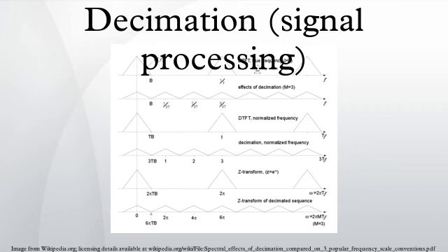Thus M low-order FIR filters are each filtering one of M multiplexed phases of the input stream, and the M outputs are being summed. This viewpoint offers a different implementation that might be advantageous in a multiprocessor architecture. In other words, the input stream is demultiplexed and sent through a bank of M filters whose outputs are summed. When implemented that way, it is called a polyphase filter.